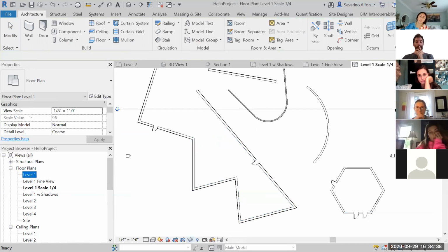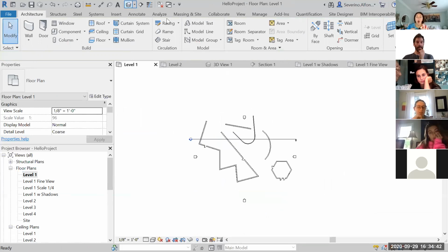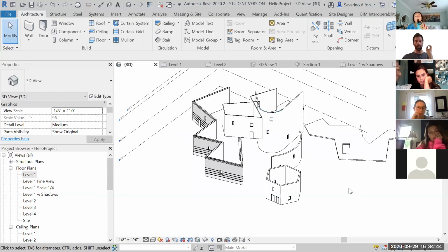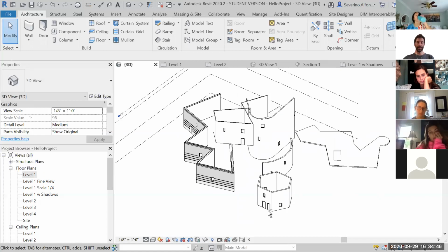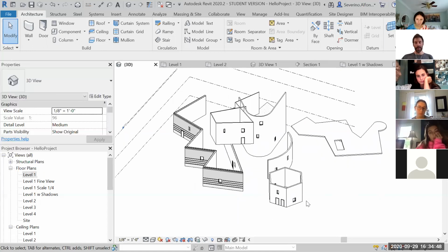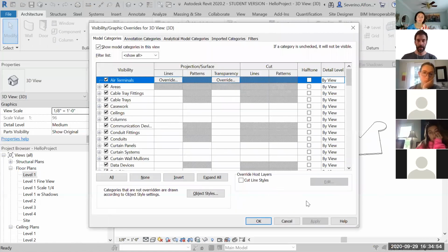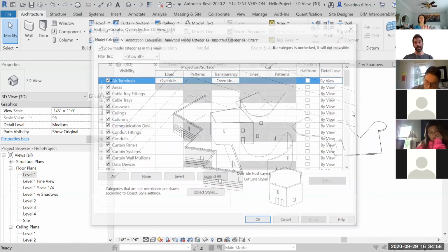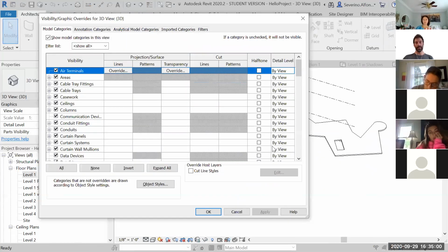I never explained about the glasses and the light bulb, which is very important. So let me go and do that carefully because it also relates to one important thing in Revit. One important thing in Revit is what is called visibility and graphics. Shortcut VG. If you click VG or VV, as in victory twice, you open this panel.